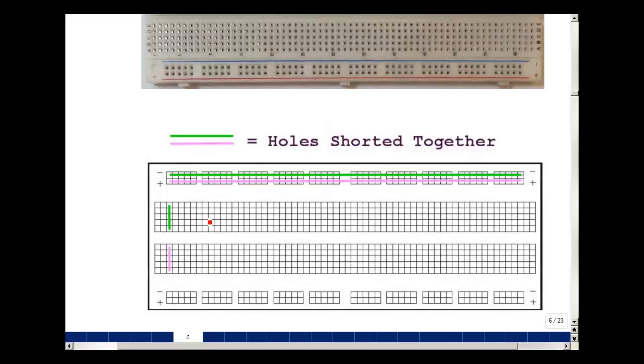Let me show you an example. So as I put a resistor in this hole, and take the other end over here. Now I can put 4 more things into here. They'll hook up to this resistor, and likewise over here. A lot of these rows here, they're short rows with 5 things connected together, and some with spring clips, so it makes a nice firm connection to the wires that we're sticking in here.